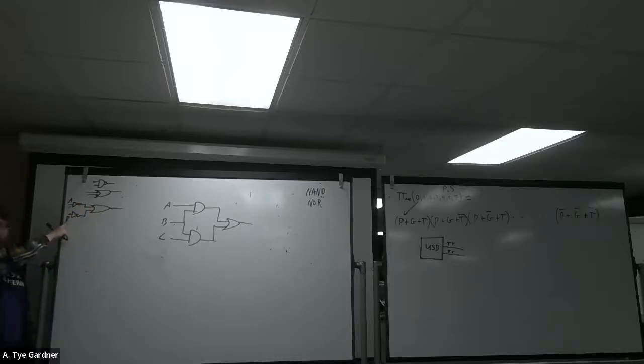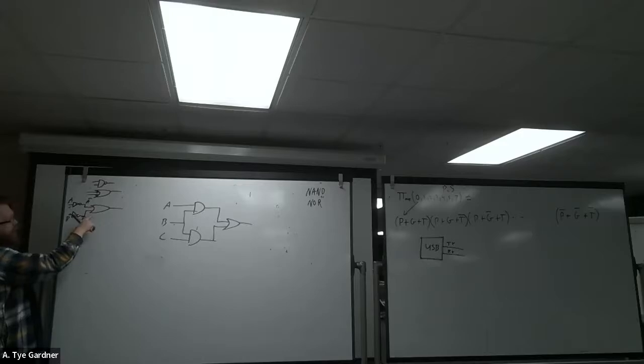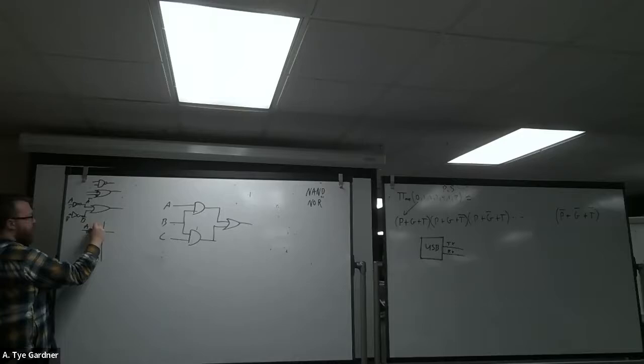Stick inverters at the input, right? Because that's all those bubbles stand for, is they're just inverters. And then see if the truth table for a NAND gate and this gate are the same thing, right? And we would do that because this is now not A and not B. And then we just say it's true if and only if not A and not B are both true.